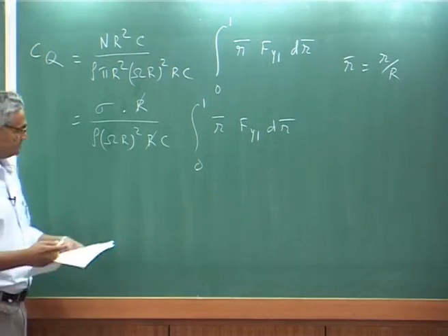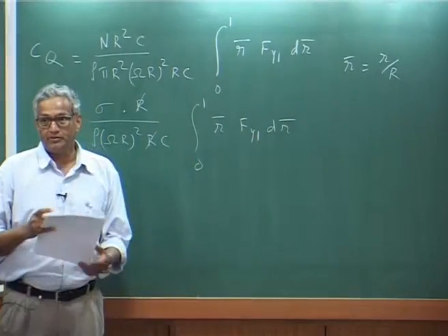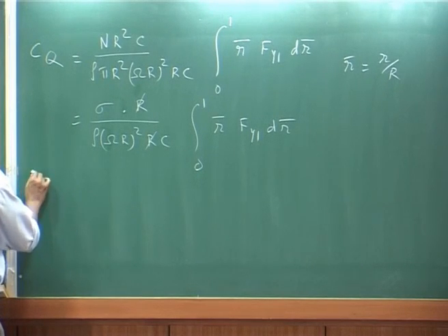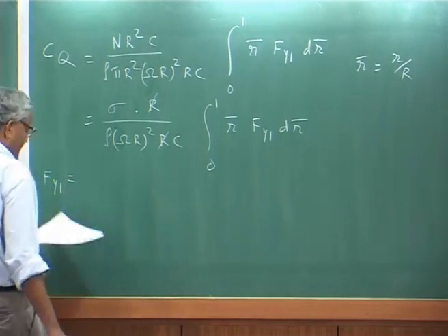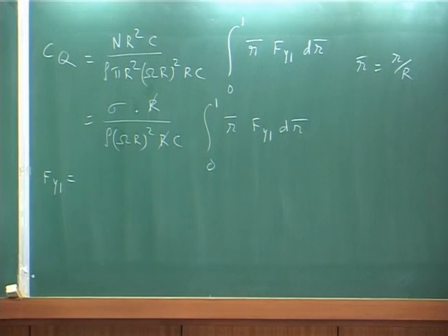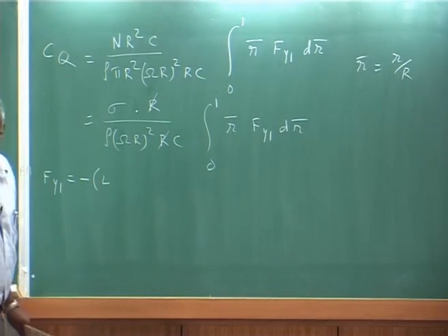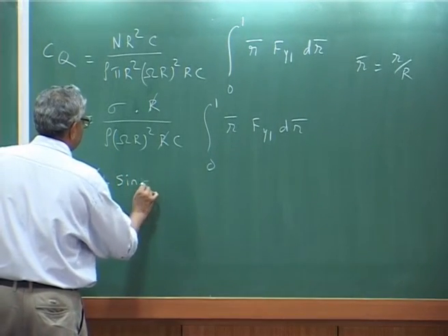Now, let us write our f y 1. We had defined earlier f y 1, if you go back, that is nothing but the drag force. Okay. Look at your notes, it is essentially, where is your f y 1, yeah, f y 1 is minus L sin phi plus d cos phi. Okay.